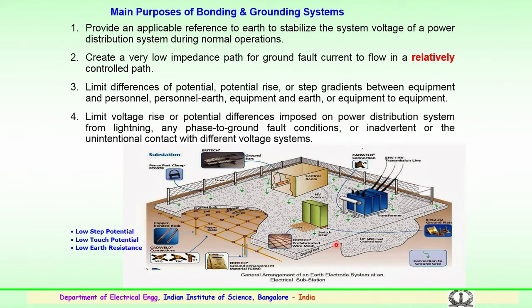So, if any phase to ground fault happens, or inadvertent or unintentional contact with the different voltage systems, the over voltages which are developed should be safely connected to the ground so that the equipments do not get damaged. So, very important aspects.